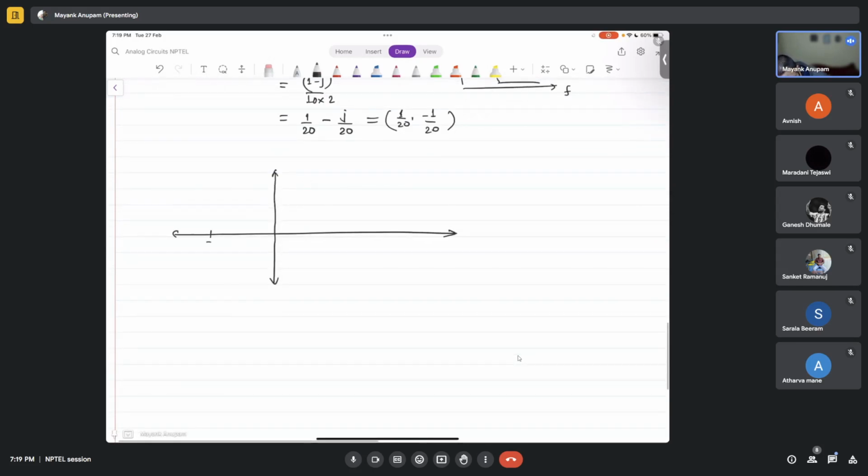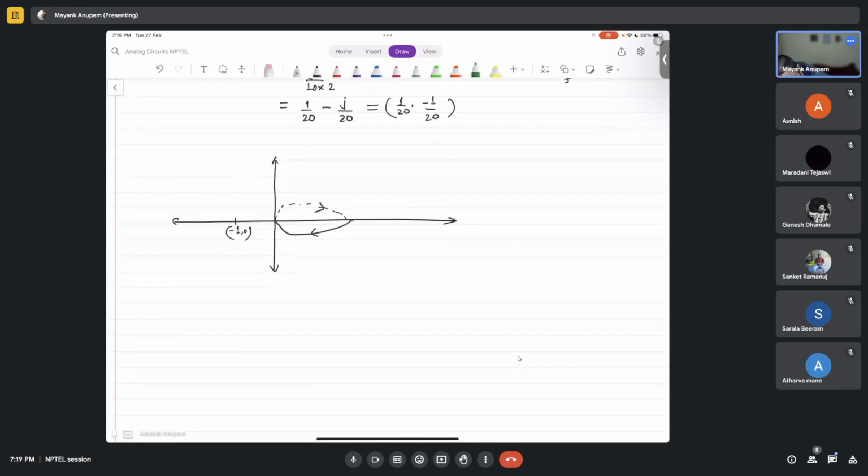Okay, let's say you have an LFS of this kind. This is the minus 1 comma 0 point. We had this LFS, right? This is the LFS that we had. But you can also have an LFS which is like this. If the LFS is different, then you can have a Nyquist plot which is like this. Something of this kind. But here you see that the encirclement is not anti-clockwise, it is clockwise, isn't it? So this is also stable.